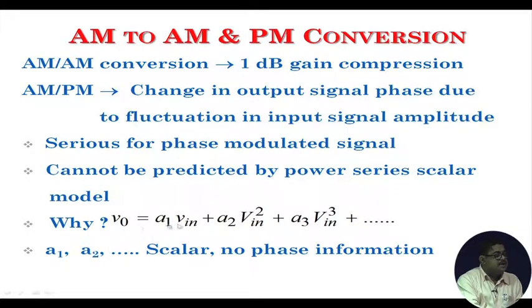If we do that, then these expressions won't be simply their square; we will have to use the conjugate relation. So, A1, A2, A3 should all be vector or phasor quantities, and when we are squaring Vin, we should remember that we are squaring a complex number.